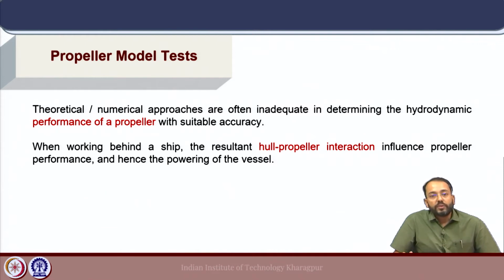And also for the propeller we have its performance in open water where there is uniform inflow condition, and when the propeller is working behind the ship hull, its performance changes because of the effects of the wake. So, the hull propeller interaction is also important in the behind hull performance of a propeller.